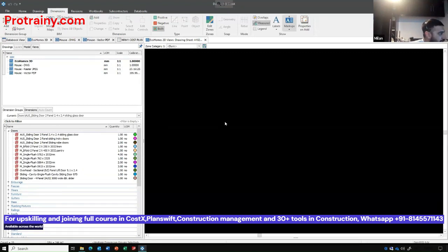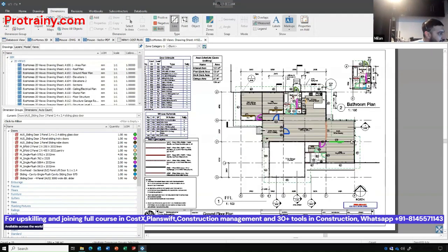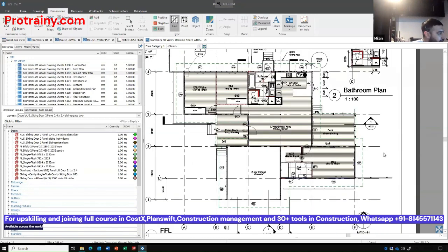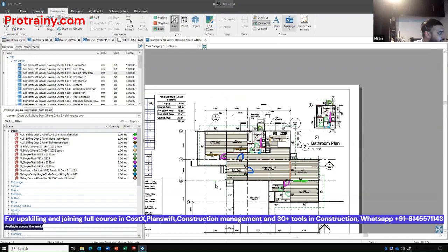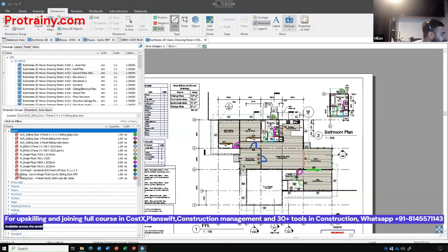What you'll notice is that the doors that have been extracted from the model will superimpose on the 2D views. So if I click on this bifold door, you can see it's here. So these are linked by object IDs. It's a very clever feature that it has, and it allows you to really look into detail about what has been measured in your drawing.